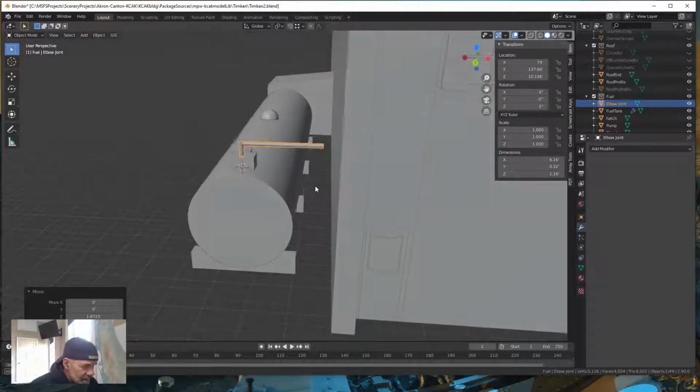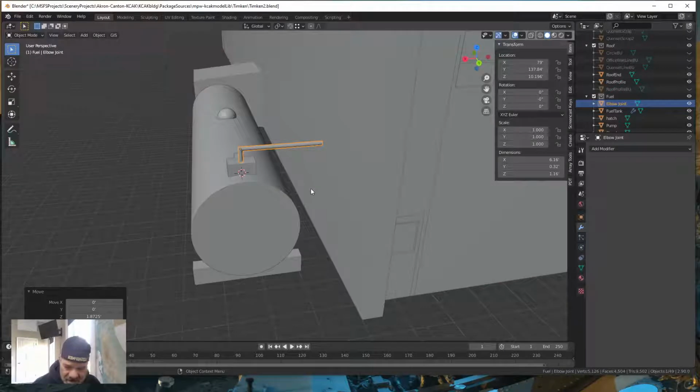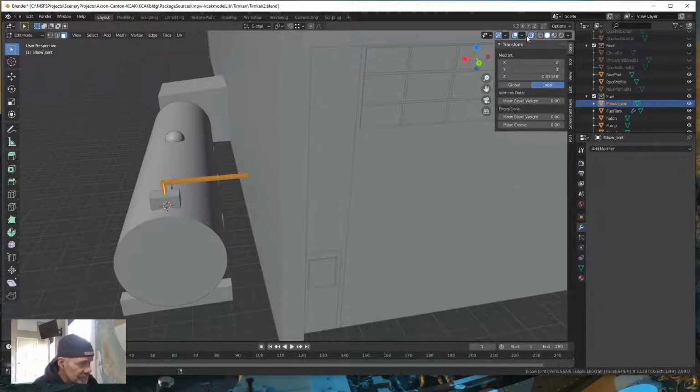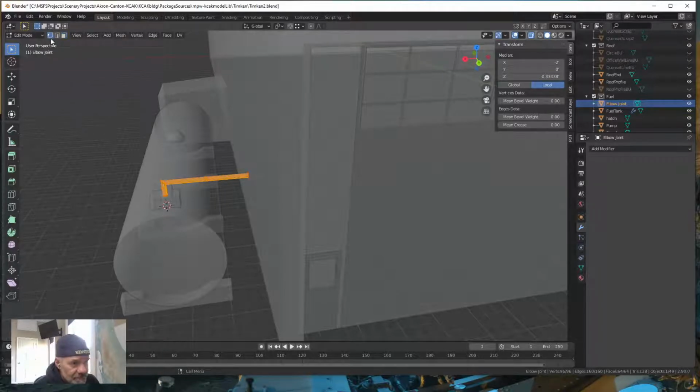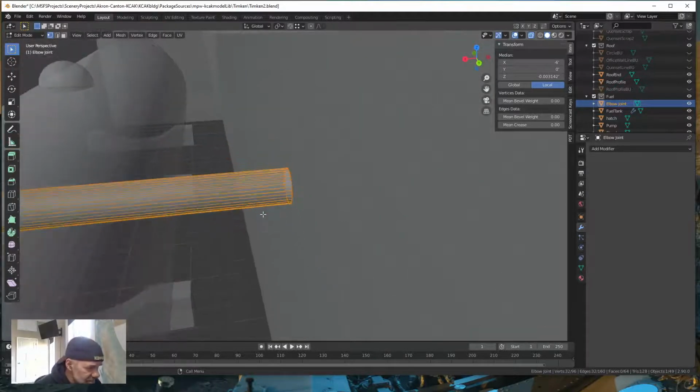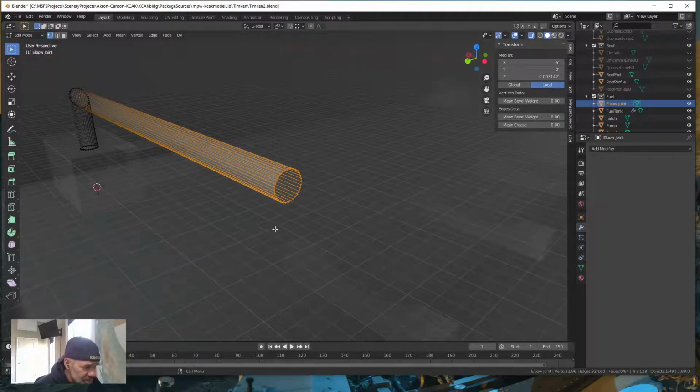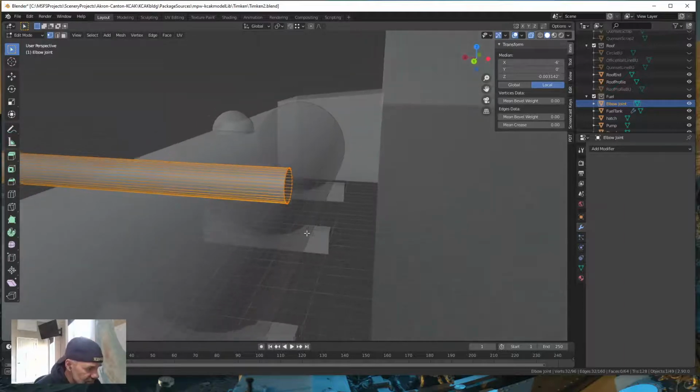All right, now I want to add another corner to our pipe. All right, but I can't add it to this object because this is a pipe elbow, right? So I'm going to add another pipe elbow, but I want it to be right here on the end. All right, so let's go into edit mode, turn on ghost, turn on vertex, select these vertices. Let's focus in on those by hitting period on the keypad. And now the pipe is open. There's no face here, okay, which is okay. It's not a big deal.